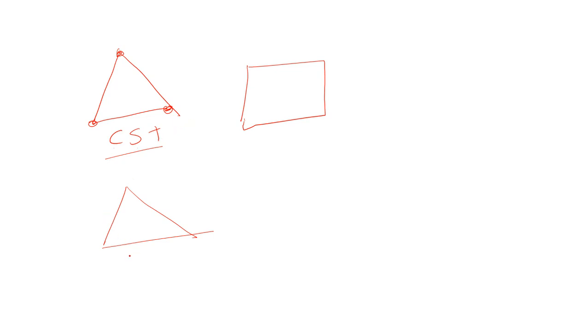LST means linear strain triangular element: in between these nodal points, at the mid of its sides, there are some more node points. This type of element is called the LST, linear strain triangle element.